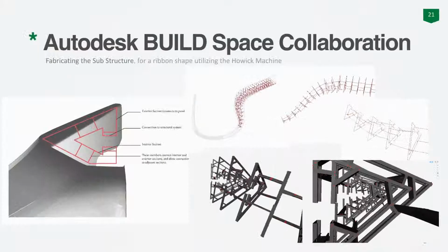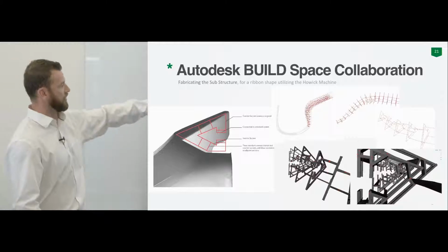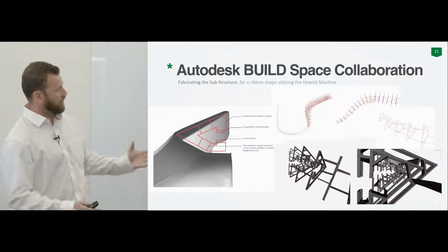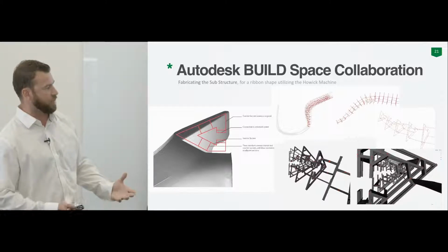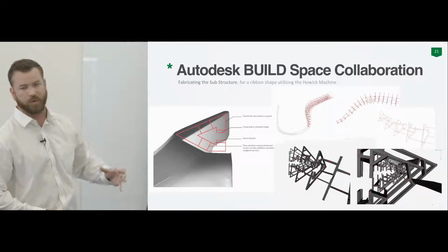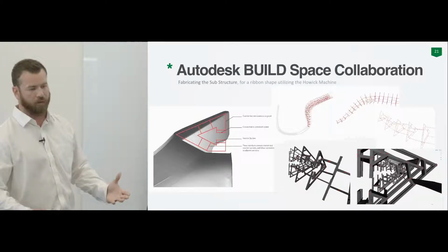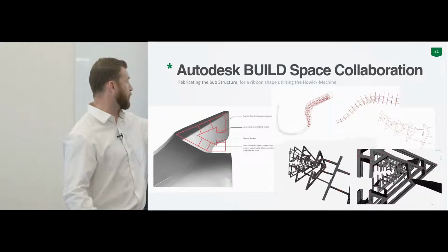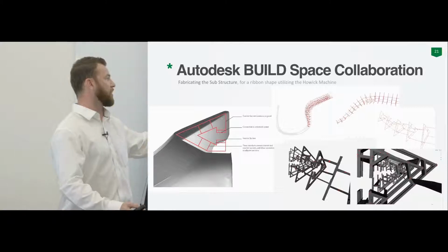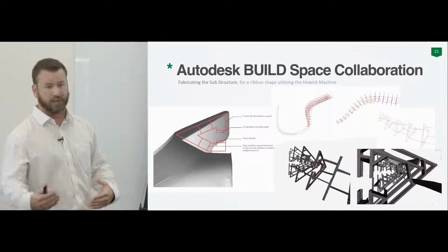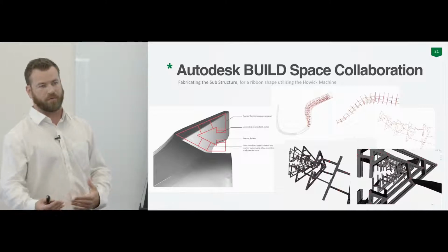Ultimately, there are many surfaces that are modeled, but you can see there's no actual framing information. It's just a surface. So they utilize a Dynamo script and cut various sections along this undulating sweep. Then you can build different parameters into it. You can offset from the face of finish, say 6 inches, let's say this was going to be FRP or some different finish. You figure that into the design, and you set the structure however far back from the surface you want.